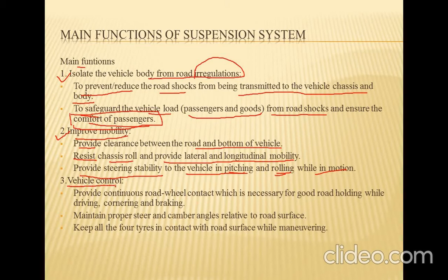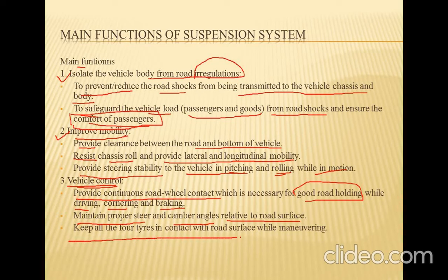Vehicle control, the main function, that is to provide continuous road wheel contact, which is necessary for good road holding while driving, cornering and braking. So proper balancing should be there under the vehicle control. Then it is to maintain proper steer and camber angles relative to the road surface. Then it is to keep all the four tires in contact with the road surface while maneuvering.